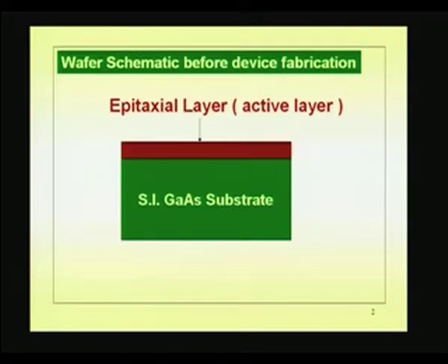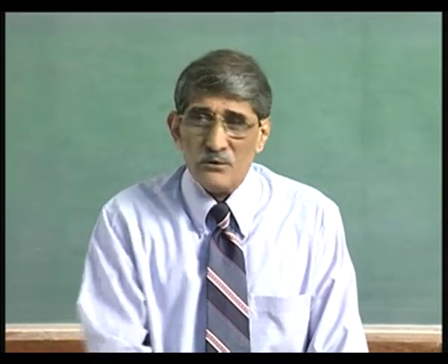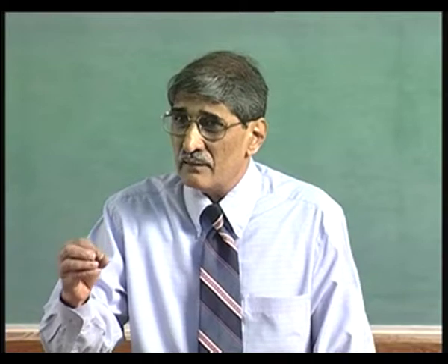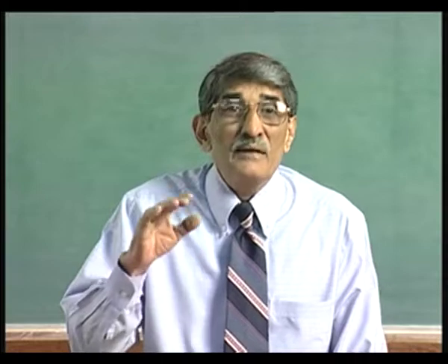Now, you transport these constituent elements, it is not enough if you transport them, you must give opportunity for these constituent elements. Let us talk of silicon, because only one element you have to talk of. The silicon atom you have transported onto the surface. What does it do? If you just transport the silicon atom, it will go and rest there. Okay? That is not epitaxy. It is just dumping silicon there. You do not want to dump silicon, you want to have silicon arranged with the same arrangement as that of the substrate. How can you do that?